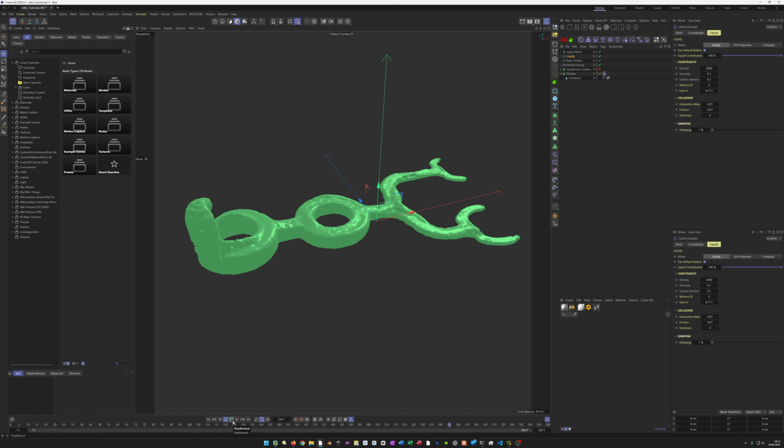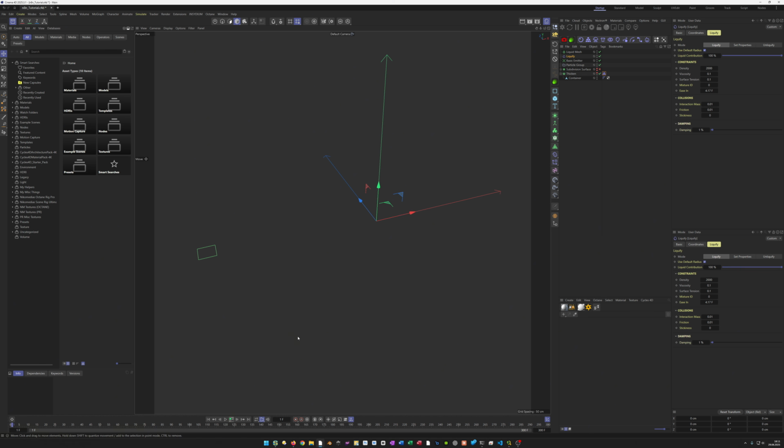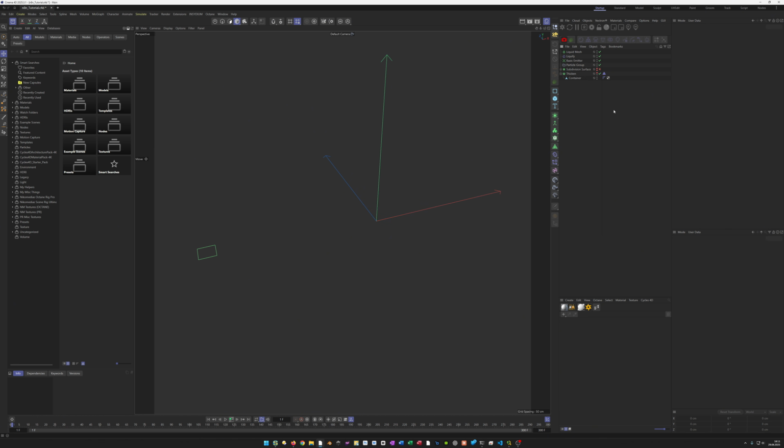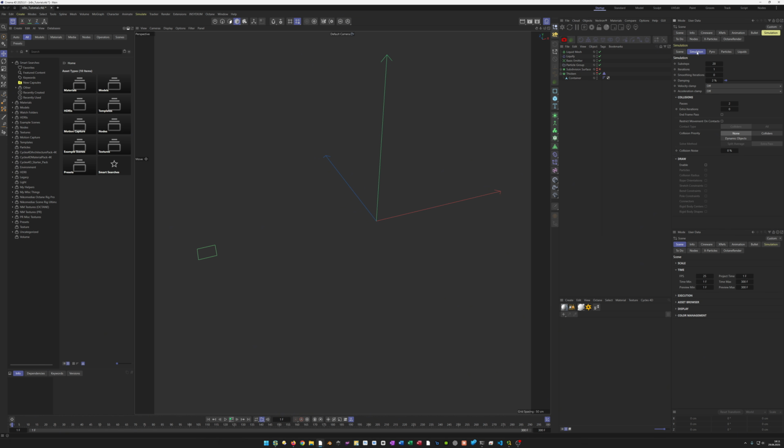But it feels too slow. And my trick was, let's save this. I don't use the gravity from the scene. So with Control D, we go in the scene settings. In the simulation scene, we disable our gravity here.